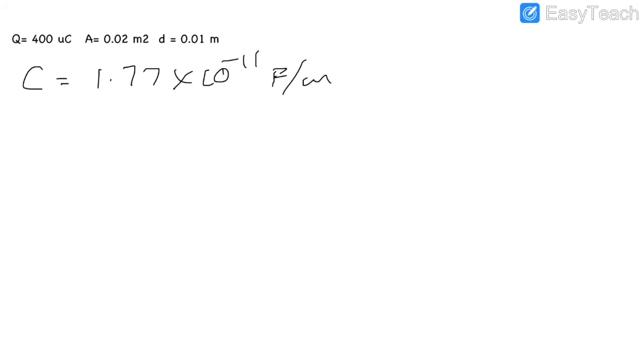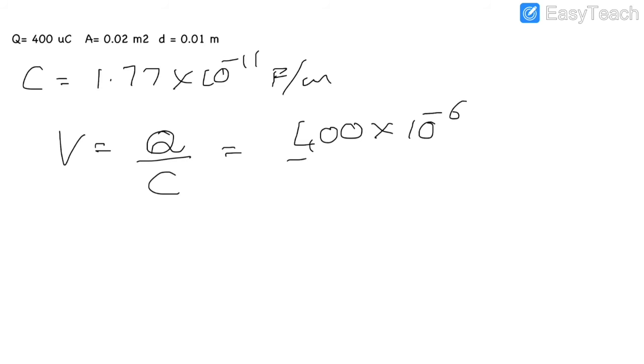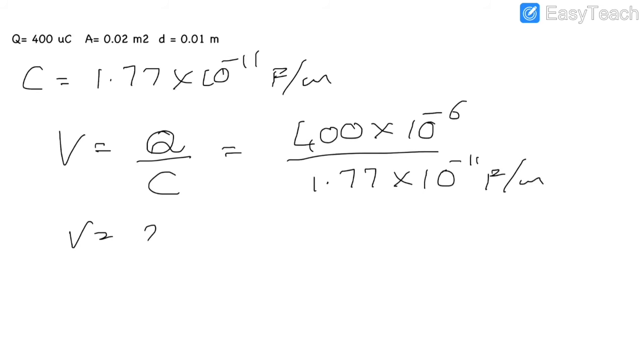Our voltage or potential difference is nothing but charge divided by C. The charge is 400 microcoulombs divided by C, which is 1.77 times 10 to the power minus 11 farads. And this is going to give you 0.6 times...